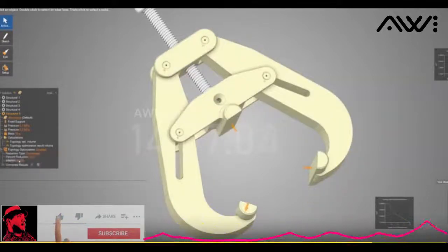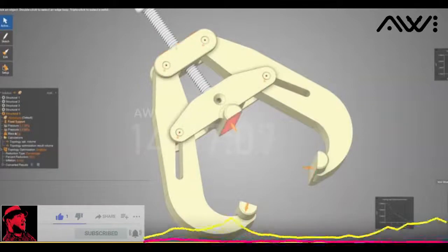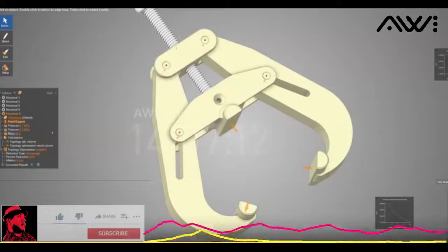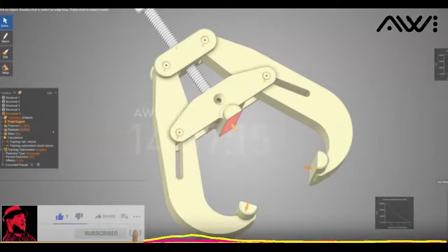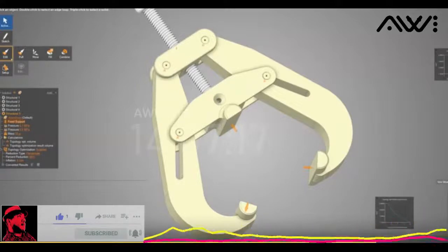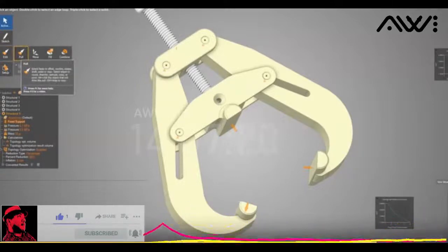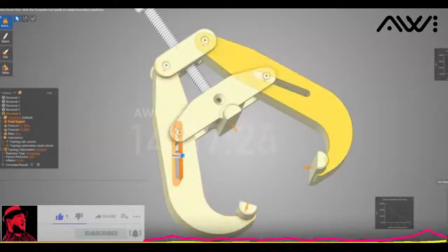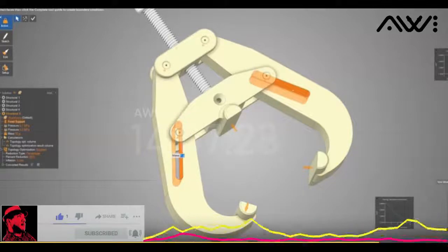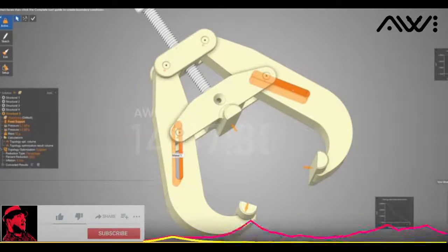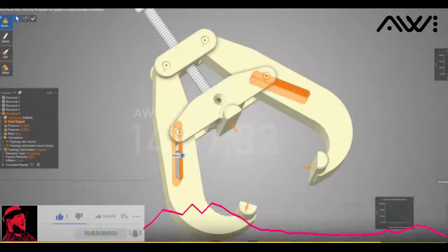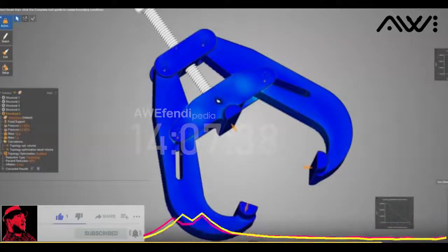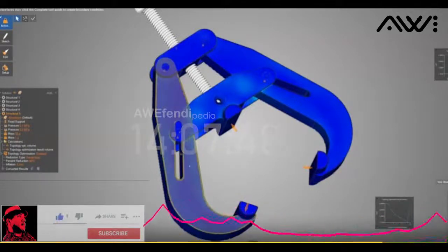So if we look at the regions here, the masses, what I can do is create another keep out region that I don't want to be inflated too much. In general, under setup, we can go under mass and I'm gonna say, well, where's the mass gonna be? Maybe right here. I'll hold down control, pick this up here and apply just a small amount of mass, because that's gonna be moving around. And then when we go back through and run the topology optimization, you're gonna see exactly it's gonna keep the area out.